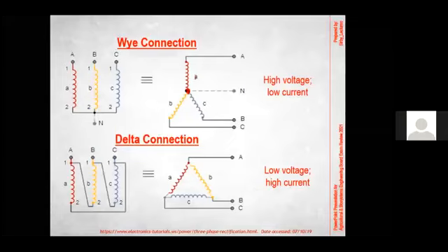Right here, you can see the subscripts A, B, C, and that refers to the phase voltages. V phase refers to phase voltage. So we have phase voltage A, phase voltage B, and phase voltage C. And right here, from A to B, we can have another voltage term, and that's what we call the line-to-line voltage.